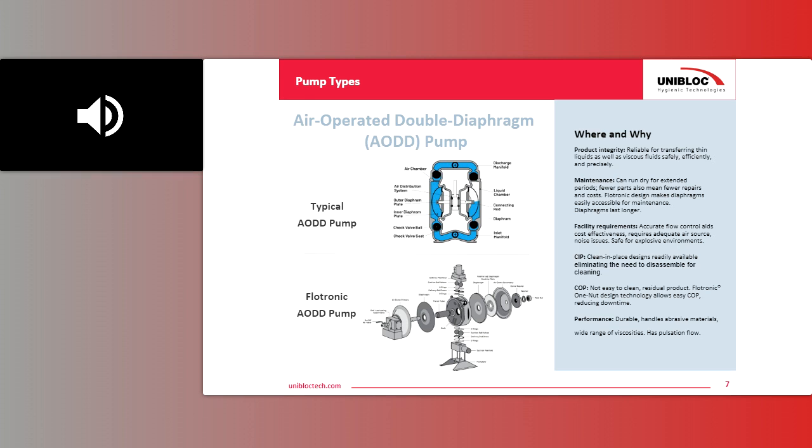I like to call it one of the most forgiving pump technologies. What we mean by that is it does have run-dry capabilities. It does have the capability to deadhead the pump, and neither of those will damage the pump for more extended periods of time compared to other technologies. It is an air-driven pump, so it also applies to what we call classified areas for explosion-proof, or you're working with volatile chemicals. Air-driven versus electrically driven aids to that ease of use in those industries. It's much easier to configure that for an explosion-proof or ATEX type environment.